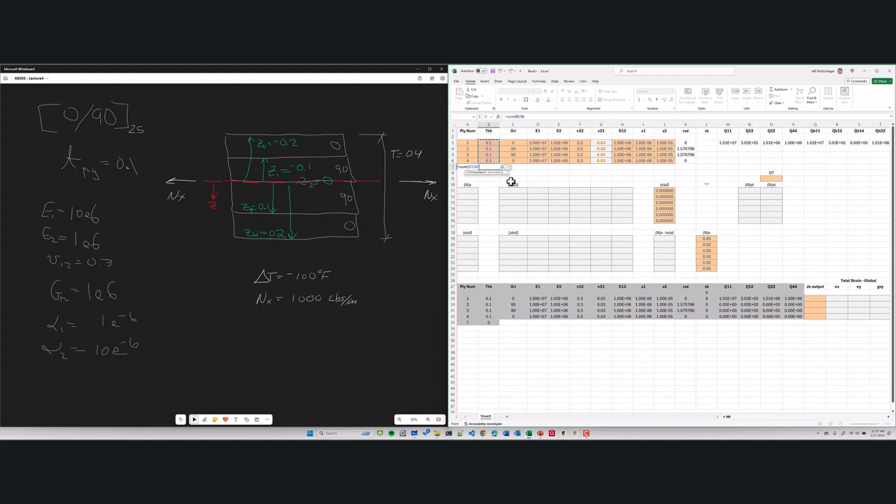And of course, this is going to be 0.4. So now the middle surface is always our datum plane. And I might not have made that clear in lecture, that the middle surface is always our XYZ. And that's really our Z of 0, right? And so everything goes off of this middle plane. Well, our middle plane, I have 4 plies, is in between ply 2 and 3.